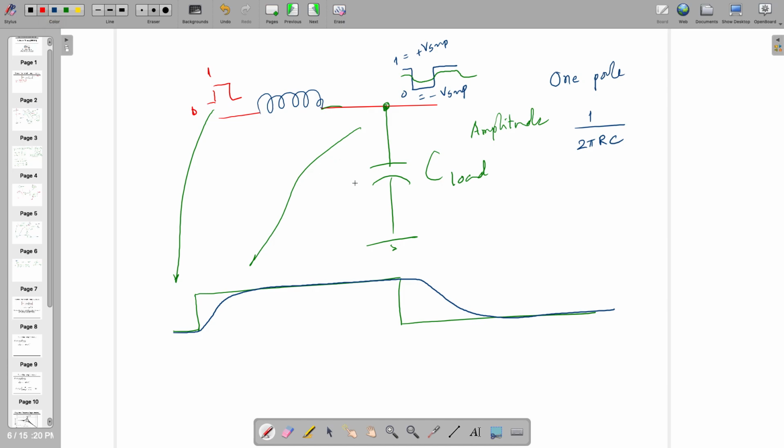This very famous thing, right? You have done it in your school. No, no, somewhere. So you have to write down the transfer function. So V out divided by V in is equal to 1 by SC divided by LS plus 1 by SC is equal to 1 by S square LC plus 1. Now somebody can help me in finding out the pole locations.